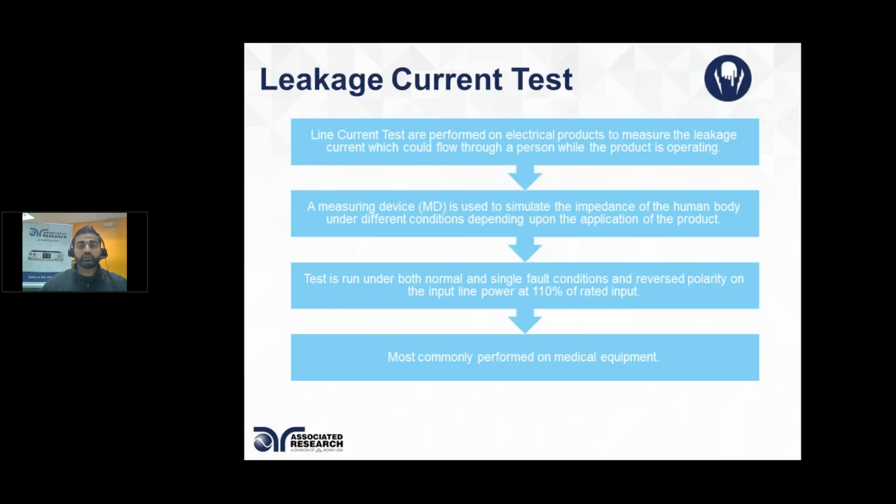If those metal knobs are connected anywhere to the circuit, I want to make sure I don't get shocked. So a leakage current test is designed to let you know how much leakage current will flow in the event that a ground pin was broken, or somebody didn't wire up the ground properly in your house, and you go up and touch the toaster.